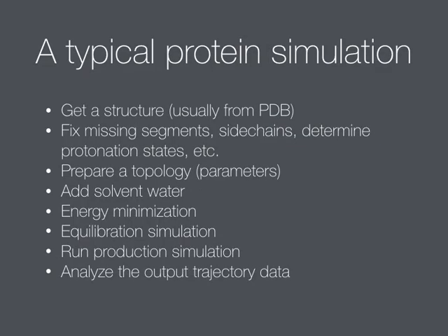Okay, so how does a typical simulation look? Well, it usually goes like this: get a structure, usually from the PDB file. This is also what you'll do in the labs. I think the structure is provided there, the PDB file from the PDB database. You often need to fix missing segments. For the exercise we of course don't have that, but often in experiments you can't see certain parts of the protein or they're not very well resolved. You need to prepare the topology, which is basically preparing the model, but there are usually automated tools for this in GROMACS, and many packages have that.